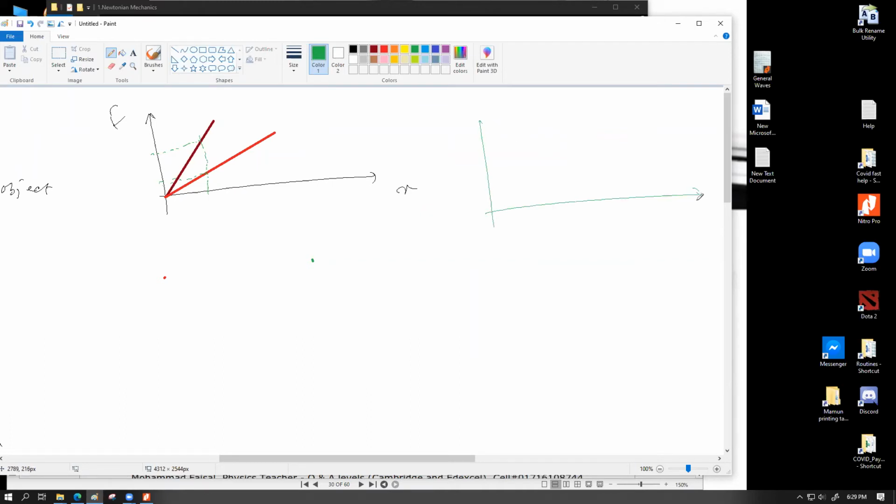If I now consider the actual graph for a single piece of wire, we have seen a linear behavior at the start, and then the graph slowly loses gradient. Whenever the graph loses gradient, it becomes easier to deform, because to achieve the same amount of deformation you do not need to increase the force by the same proportion.